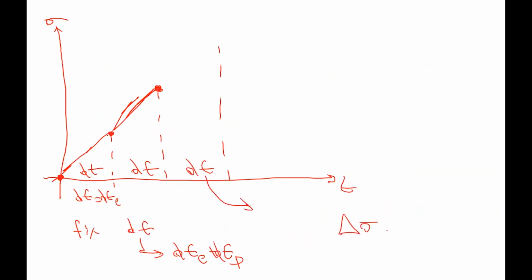It is just the elastic strain times, plus the stress at T minus 1, right? You can just delete this one. Then what is elastic strain here? Total strain minus the epsilon plastic.